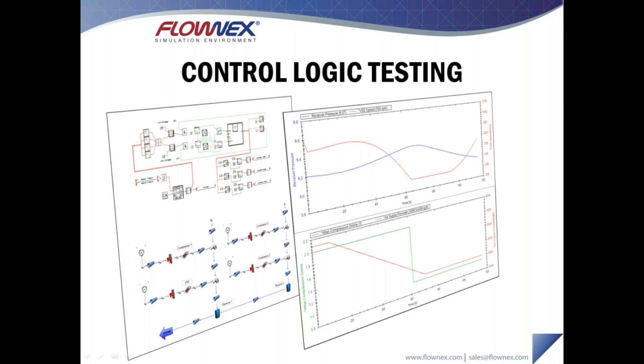So you're able to test new control philosophies for the plants, perhaps suggest ways to improve the efficiency of the plant. Perhaps you want to adjust the delays inside of this digital control section to optimize the response time between load changes, or perhaps the pressures inside of your actual compressed air receivers are not constant, and you want to try and optimize that. You could look at better tuning on the PID itself. So a network like this becomes very practical.